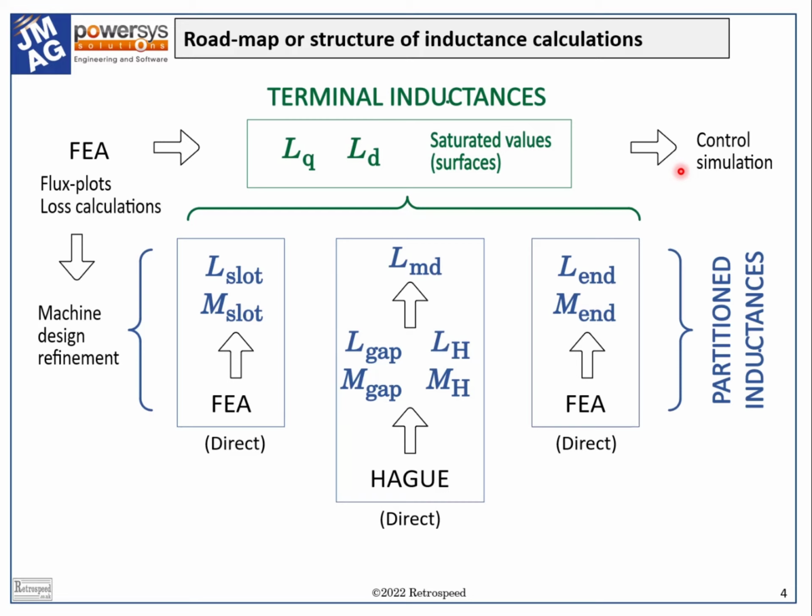For the machine performance calculation and the design of the inverter, we actually do not need the partitioned inductance components. Who, in fact, needs them? Obviously, anyone following the classical methods will need them in order to assemble the terminal inductances, as we've just described. But if we can calculate the terminal inductances directly using the finite element method, why should we pay any attention at all to the partitioned component inductances? Indeed, it appears that there are quite strong arguments to avoid them.